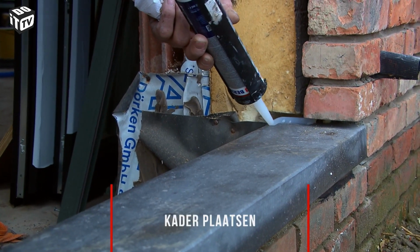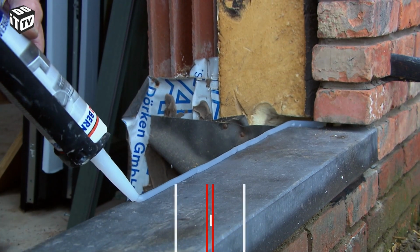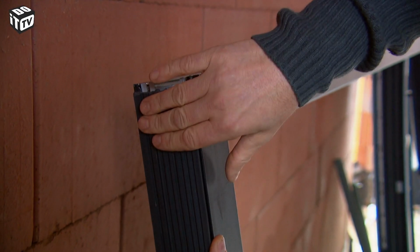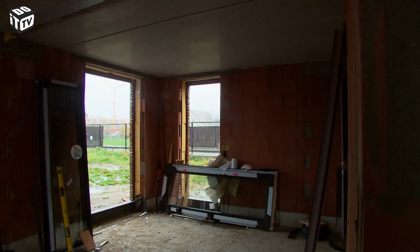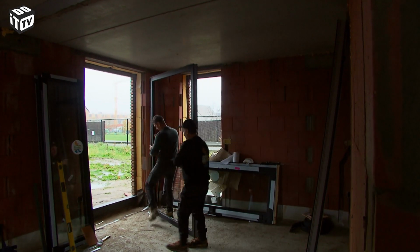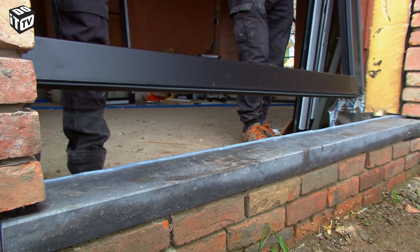For ensuring a good seal, a layer of high-quality silicone, specifically suitable for outdoor applications, is first carefully applied. An EPDM underlayer is already securely attached to the window frame itself, which also effectively incorporates channels to potentially drain moisture to the outside. Then it's time to bring the framework on site. Try to center it nicely at first glance and temporarily fix it with a few clamps.